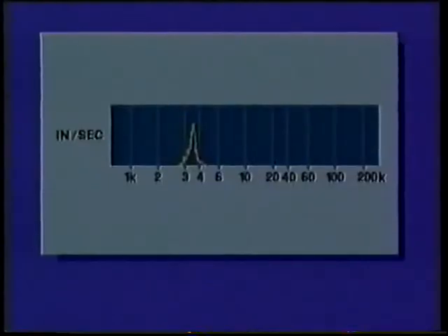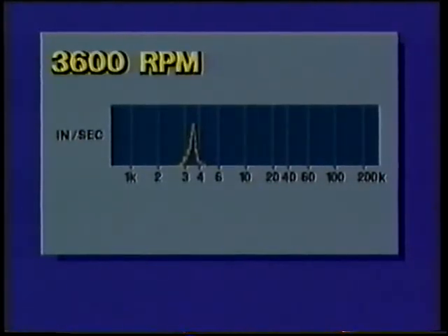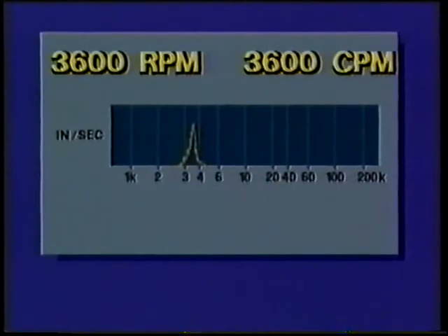While no rotating part is perfectly balanced, machine unbalance is a common cause of excessive vibration. The unbalanced shaft from which this signature was taken rotates at 3600 RPM. Since the shaft RPM is 3600 RPM and the peak amplitude occurs at 3600 CPM, this is a multiple of 1 times the RPM. This multiple of 1 times RPM is a common pattern for unbalance.